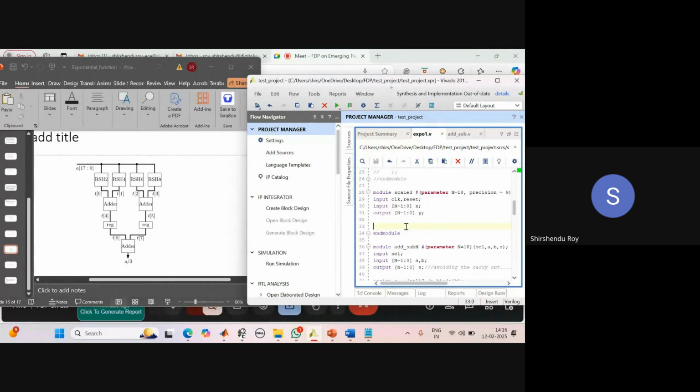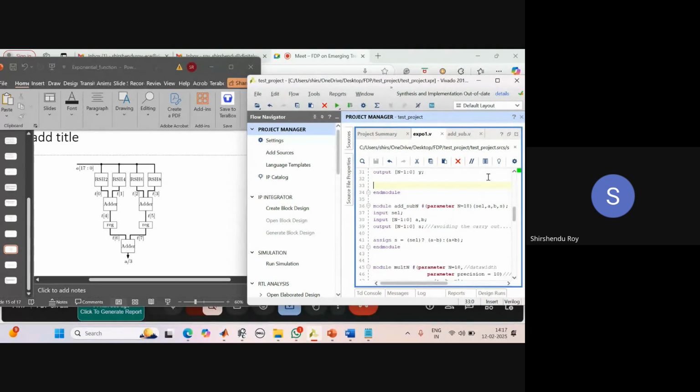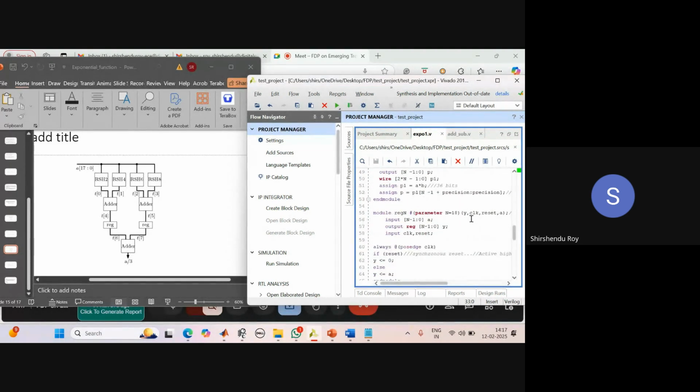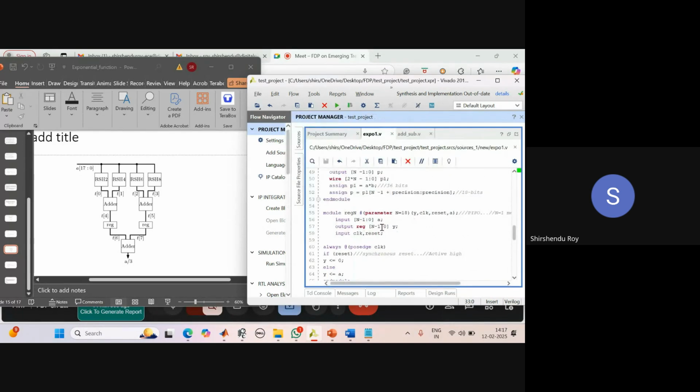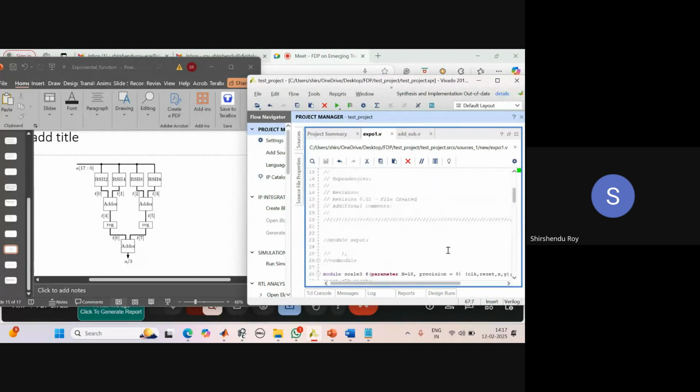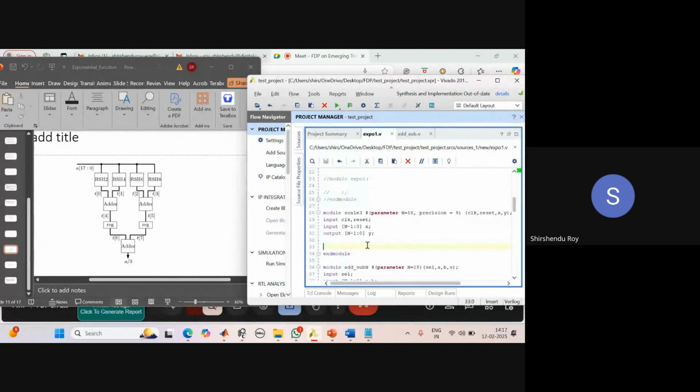What blocks do I need? I need RSH 2, 4, 6, and 8. What do these blocks do? They just shift. So first of all, I'll call the RSH block. This is the block I have for right shifting. So copy this and directly copy here.